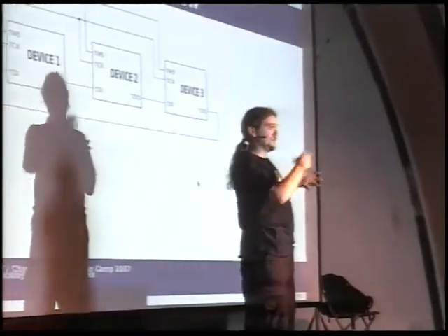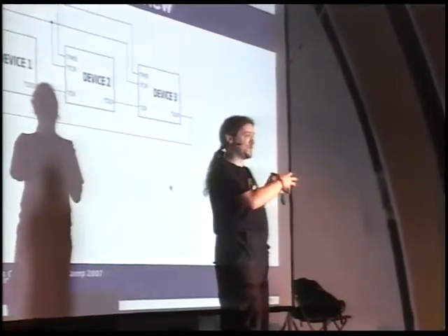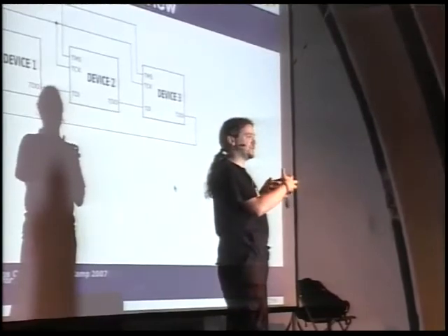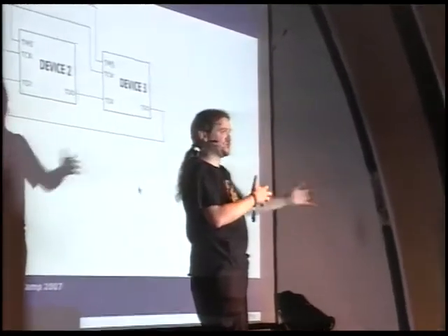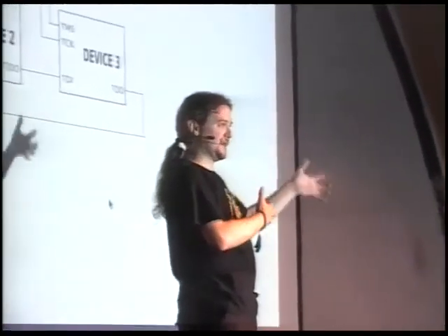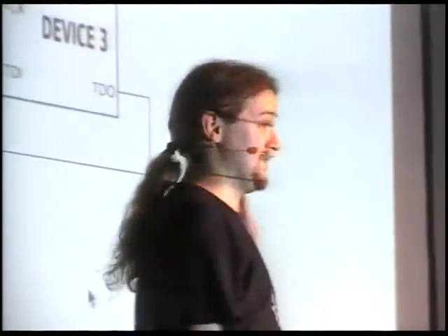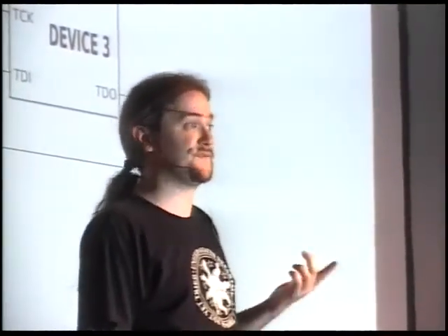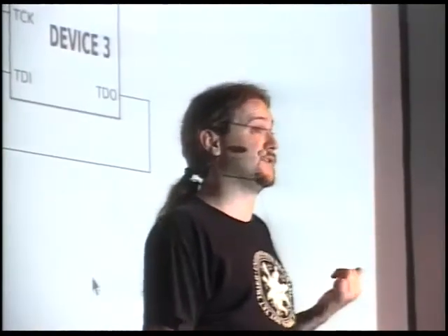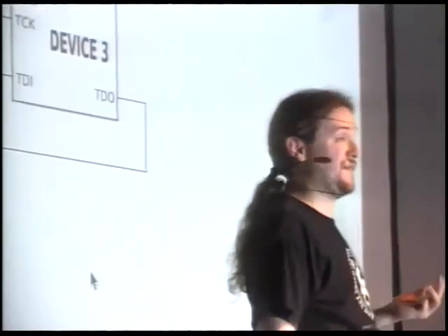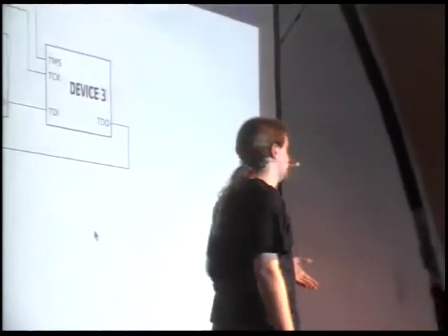Since the flash chip will be connected to something that has JTAG pins, JTAG can be used to manipulate the pins that are connected to the flash chip, changing its address lines and then reading its data lines back out through the TDO port. Needless to say, this gets somewhat tedious. It's a single-bit serial protocol, and if you're trying to read several megs of flash over it, it can take a very long time, sometimes up to a half hour for reasonably sized flash chips.